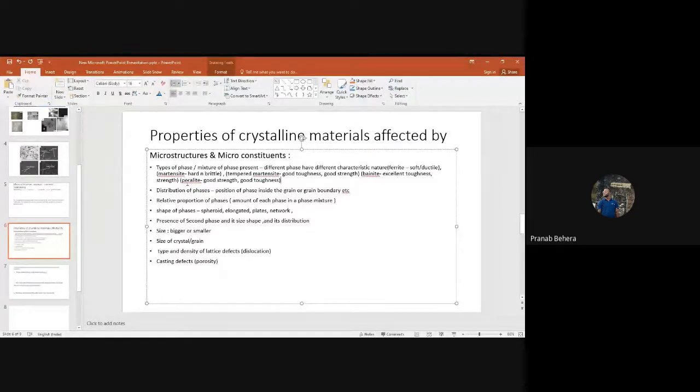These are the things, because pearlite is a mixture of ferrite and cementite. If I have more cementite, what is the nature of cementite? Hardness is high. It is completely hard and brittle. Do you remember why cementite is hard and brittle? Higher amount of carbon, 6.67 percent. That is one part. It is a single phase. This is very simple, because do you remember the structure?